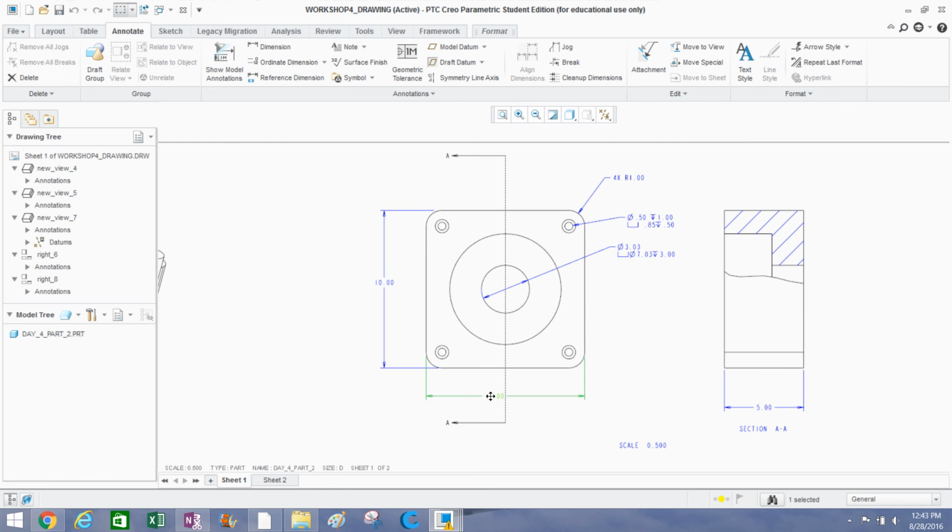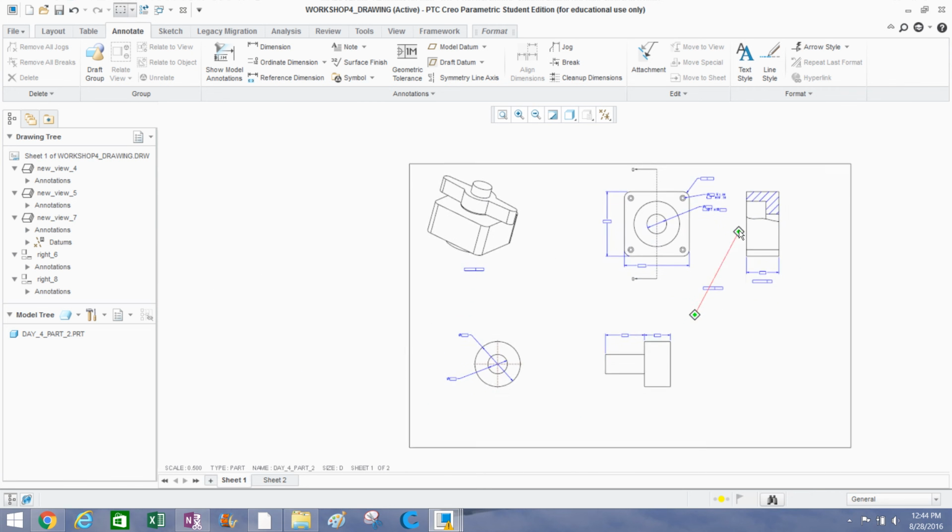Usually, maybe drag this off to the left a little bit. There you go. So now you're seeing a section. It's a partial section through A, and there you go. If you want to show something in there, I will go through the other parts. I will say you can go ahead and change a lot of things like this cross hatching, change the direction, the density, a whole bunch of other things on there.